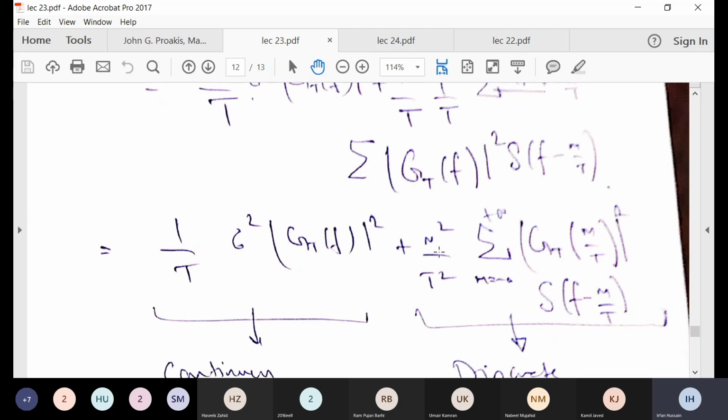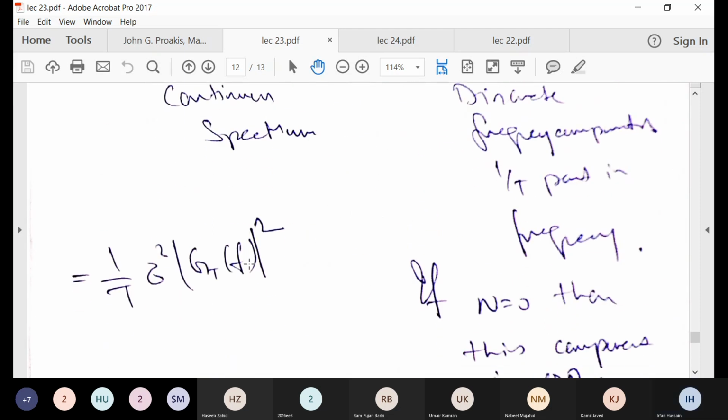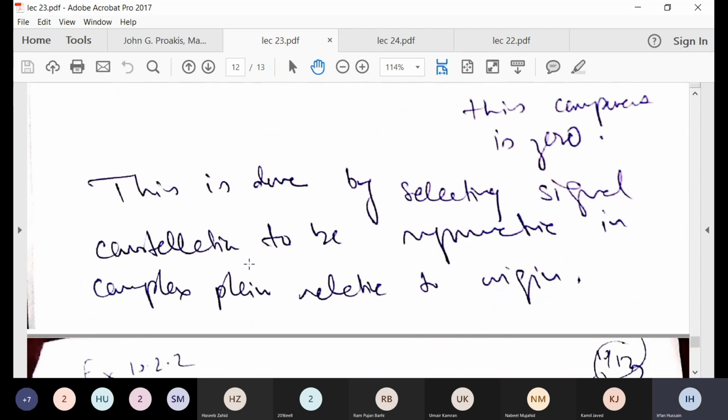Similarly, in PAM you have 4 symbols, 2 over there and 2 there, or you might have 3 symbols here and here. Again, the mean of all the signals, provided they have equal probability, will be 0. So if the mean of the data sequence is 0, then this factor will go out and you will only have this factor. Most of the time this is done so that the mean of your data sequence is 0.